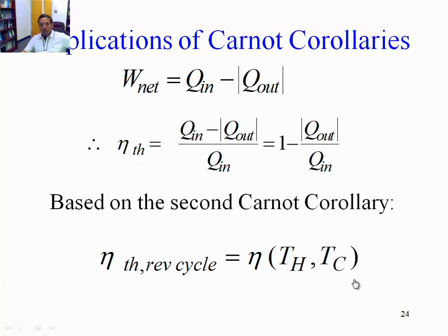Because, as Carnot stated through his observations, if you have the same two thermal reservoirs and the two cycles are reversible, you will always yield the same efficiency. It is a reversible efficiency. It's essentially unattainable efficiency because you can never get that close to perfect reversibility.